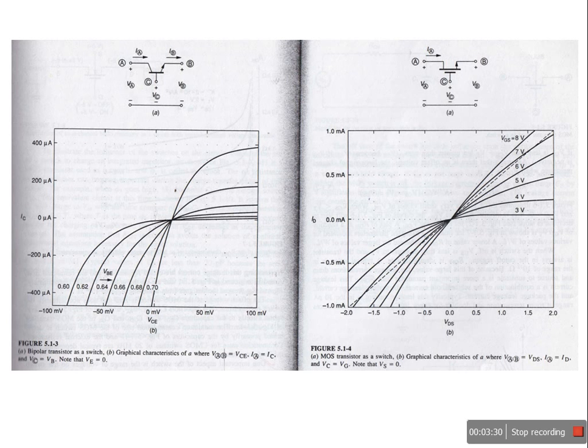So you see that we are saying that there should be no voltage or very less voltage across the terminals A and B, or across the switch we can say, and the control terminal should have appropriate voltage so that the current will flow between A and B. So what is this condition? The voltage between A and B, that is VDS, in case of MOSFET should be less, and voltage at control terminal, that is VGS, should be large. This means that VDS is less than VGS,